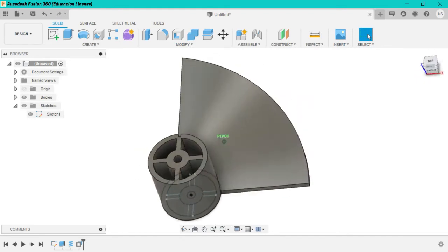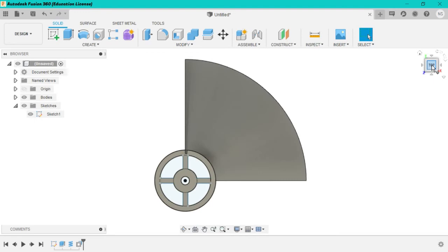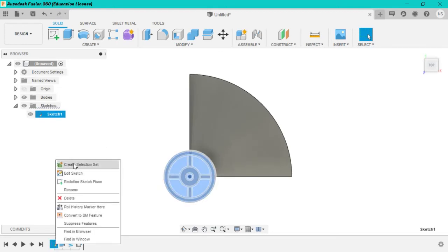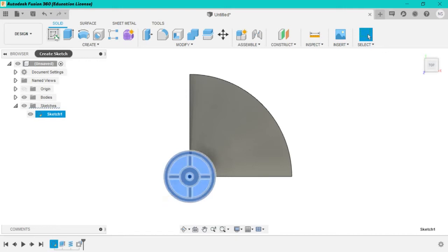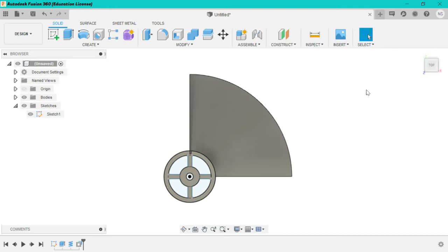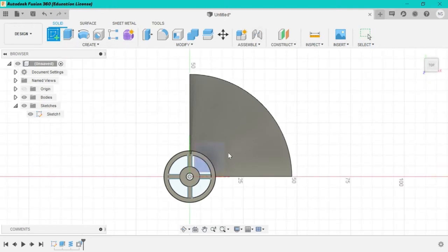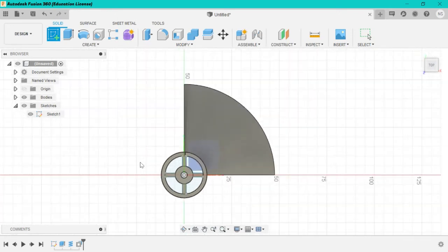This is the way we have to create one propeller, but it is not the correct shape for a propeller, as it won't swing inside water or air. So we have to give the curved edges. We will give curved edges just by cutting the edges with an extrusion tool. So we have to go back to our sketch plane, or we can click on create sketch. Then we have to create a sketch. Creating a sketch is the good option here, because if we go to the timeline, the objects will disappear, so we can't create a perfect sketch to cut out the edges.